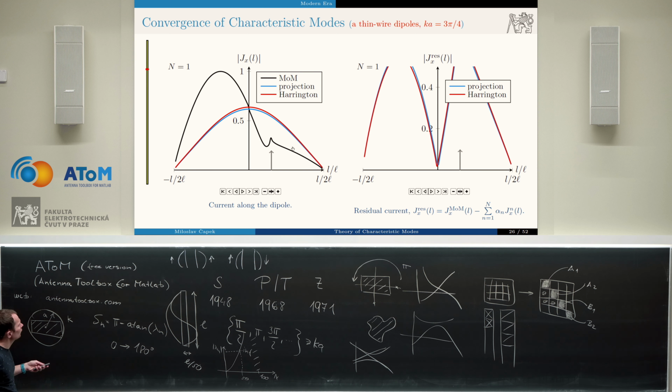And then you can really use this general formula, where once again, you can easily isolate what is the part belonging to the excitation, what is the part belonging to the modal significance of your mode at a given frequency, and what is giving you the metric itself: modal Q factor, modal radiated power, modal antenna gain, and so on. And formulating it like this, you can really easily optimize through the V vectors, for example, which are accommodating the positions of your exciters.